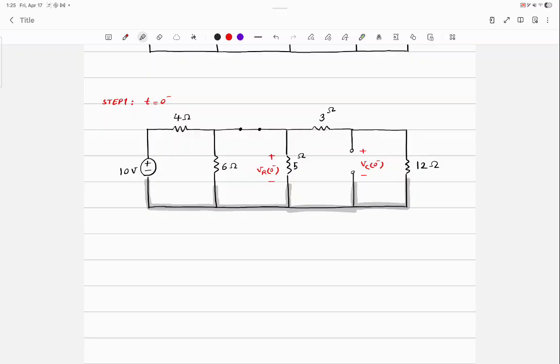Is it obvious why nodal is better? You're looking for 2 voltages. You can do them at the same time. If you go for mesh analysis, you find the currents, then you have to write another extra equations to find the voltages, right?